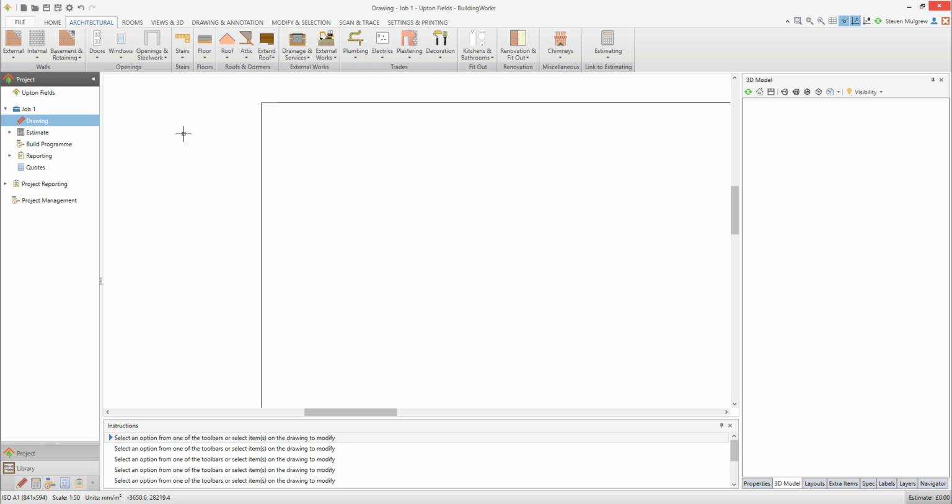I'll explain how to switch on snap mode and nearest snap so that you can locate points on existing construction lines and place additional construction lines relative to them. To do this, you'll need to use the relative tool, the R key on your keyboard. If you haven't already viewed them, we strongly recommend that you watch the basic drawing skills videos, which cover how to use the mouse and shortcut keys, before you take a look at this one.